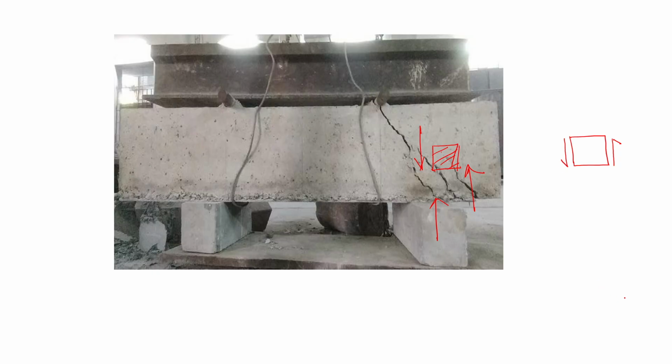Now you can see this is forming an anti-clockwise couple. So in order to balance it, or to keep that tiny block from spinning in place, equal horizontal shear stress develops along the top and bottom.